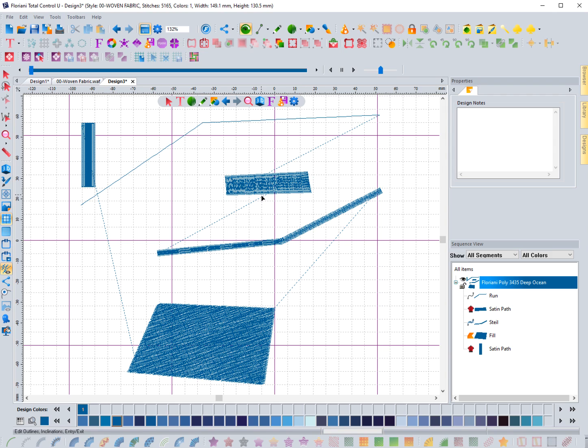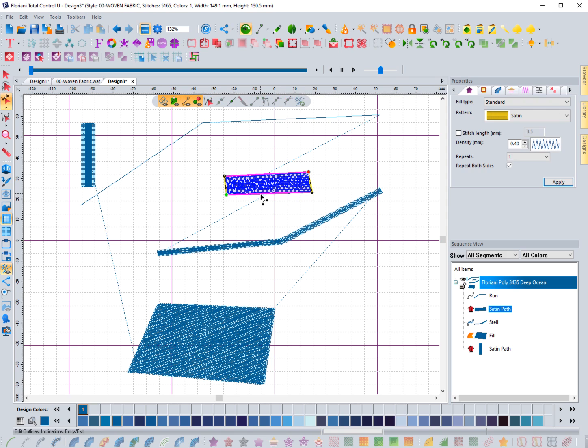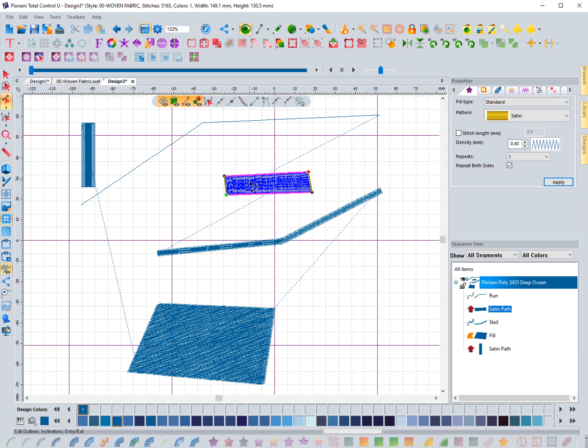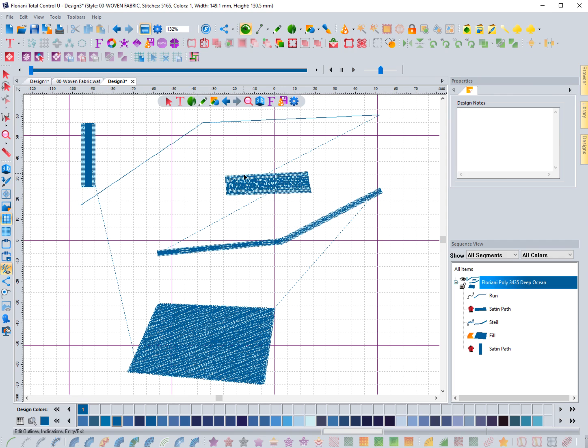So that is how you can create your own style sheet. Now, it's not perfect right now. Some of the things aren't saving, but it still will save you time, and it'll help get your basic settings already there and applied, like underlay, stitch length, stuff like that. So I hope you like this lesson. Hopefully they'll get those little issues fixed soon, and you can make some of your own style sheets. It's not too difficult to do, and get it according to the settings you want.